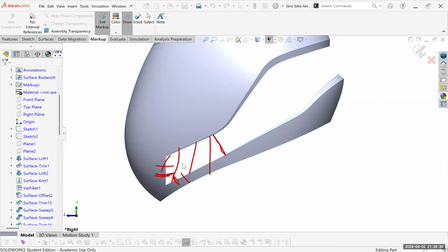And then once we built this, then we go ahead and create this back arc. And now within that, we try to do our boundary surface or fill surface. Depending on which one looks better, we also may need another guide curve here. So to create this guide curve, we're gonna come in and split the surface over here. So we can do a curvature continuous guide over here.